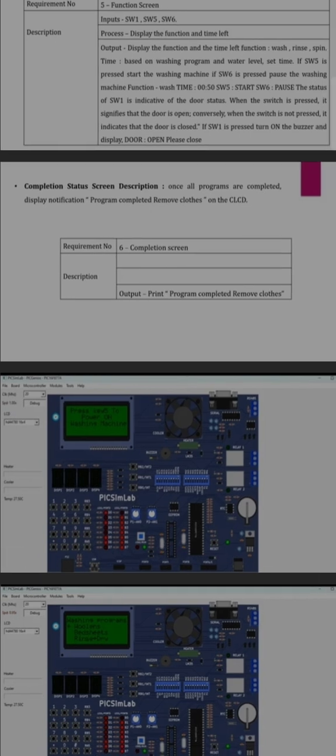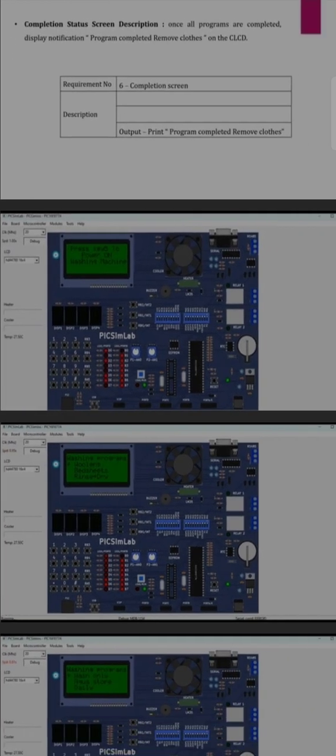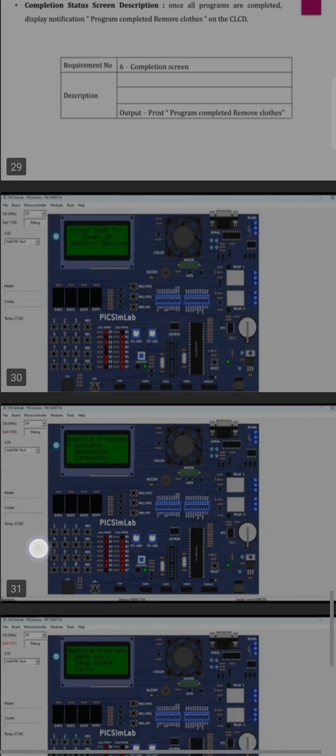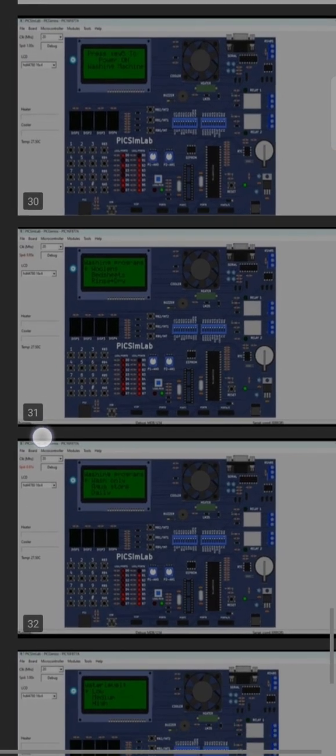Going to the PIC16F877A software. Once you have installed the PIC16F877A software in your system, select the clock frequency in megahertz and give the LCD code. The code will be loaded onto the PIC16F877A microcontroller. After that, select the switches you want to press. After the washing machine is programmed, you click on switch numbers and it will indicate rinse or bed sheets, woolens or dry or spin.